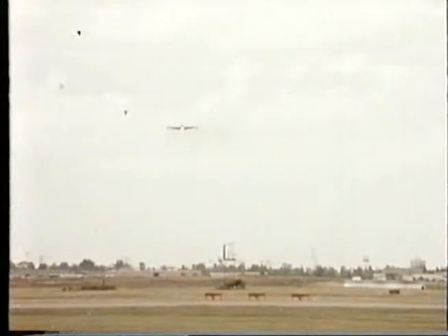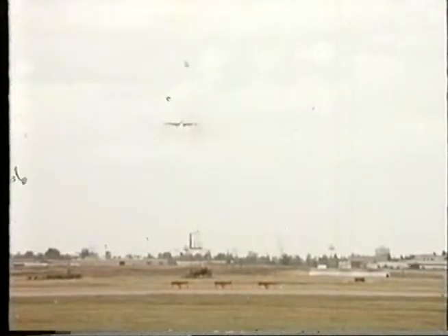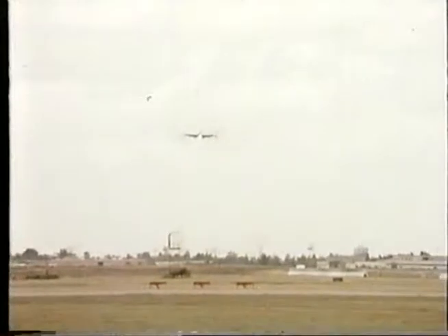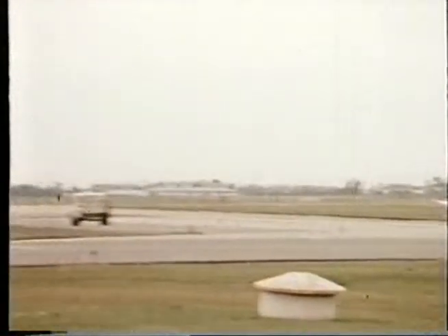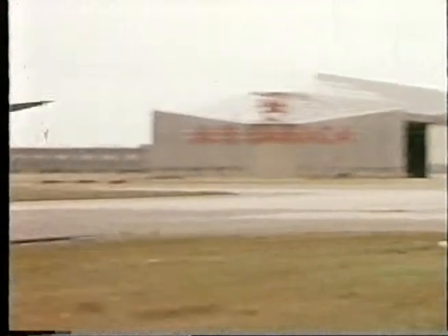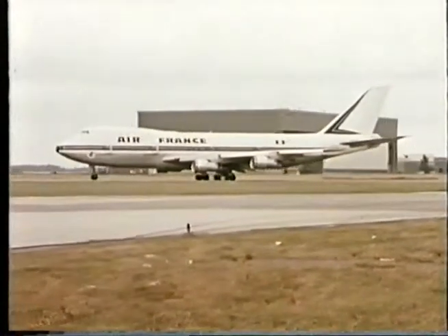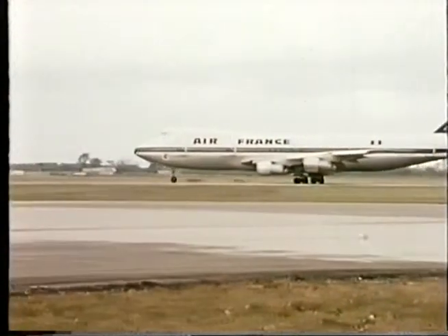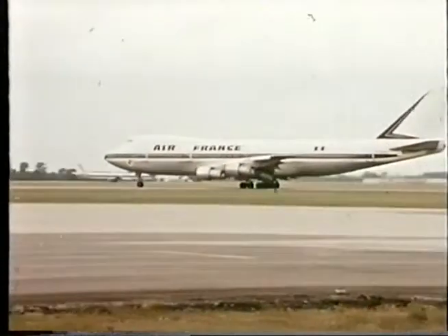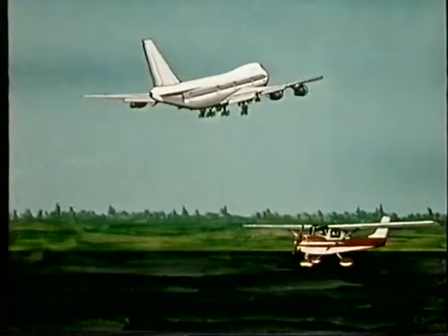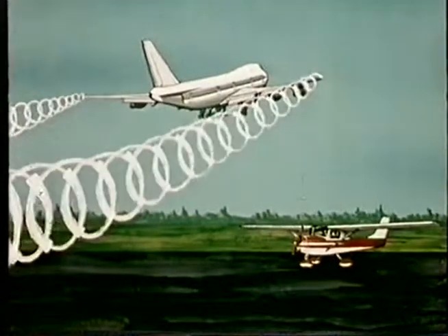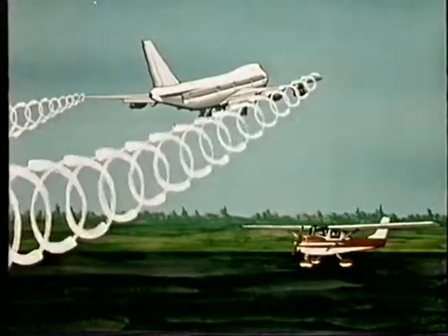The separation minima dealt with so far are designed to provide safe spacing of aircraft to prevent collisions. However, the aerodrome controller must also, when necessary, consider wake turbulence, and especially when a light aircraft is following a heavy jet aircraft, apply a greater separation. In conditions of little or no wind, wake turbulence has been known to persist for several minutes.